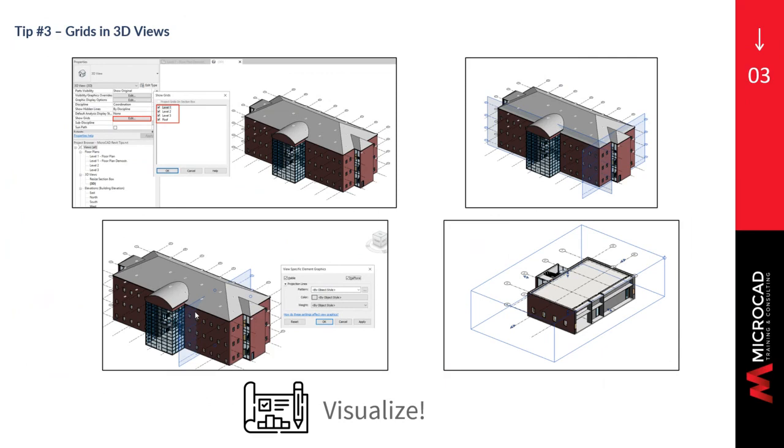And when you select the levels of which you want to show the grid lines, it's going to display the additional grid levels. And this setting is going to apply to all the grids in your project, but only the ones that you selected. So you just have to make sure that you want to show them.